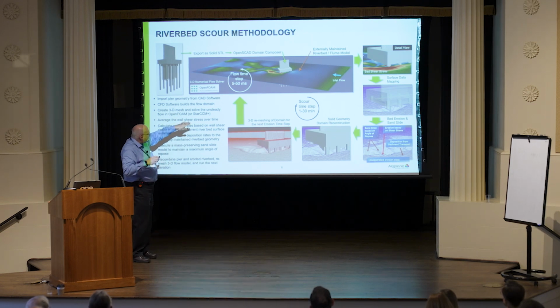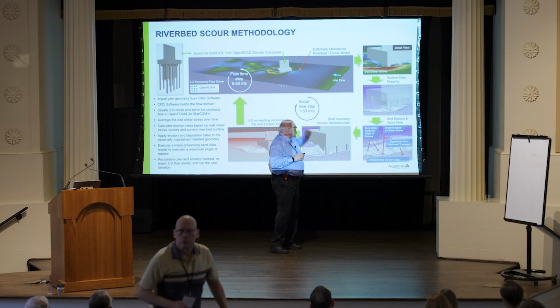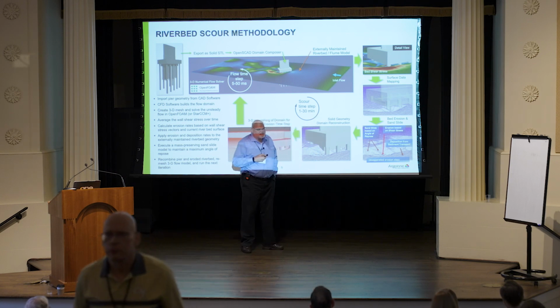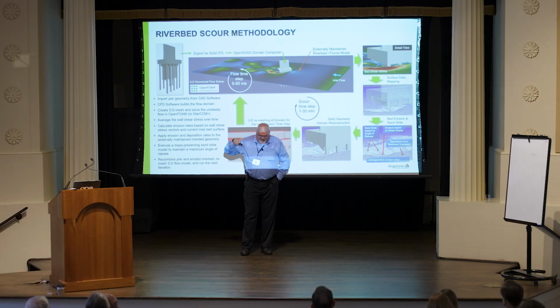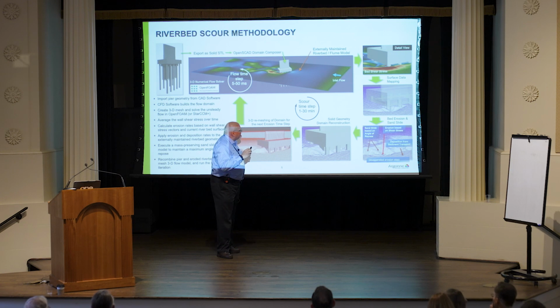I mean, this is just the river bottom, but this is a three-dimensional calculation of all the patterns on how the water develops eddies and runs around the pier. So what we're really looking at, and that's what you see on the upper right, are the bed shear stresses. We have to accommodate for going downhill and uphill in the direction of the shear stress vector, but that gives us a very good pickup function for the sand.